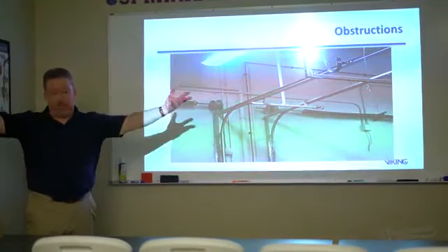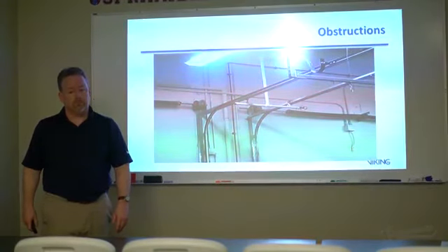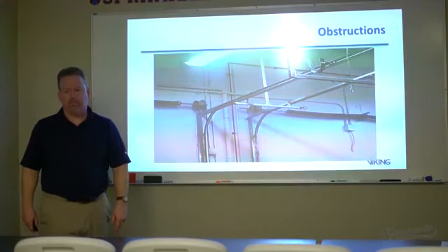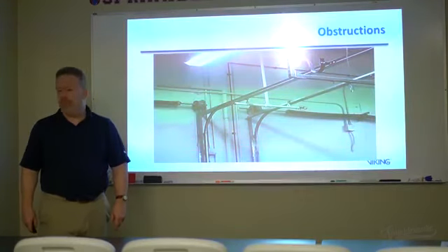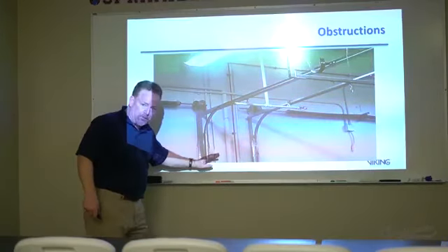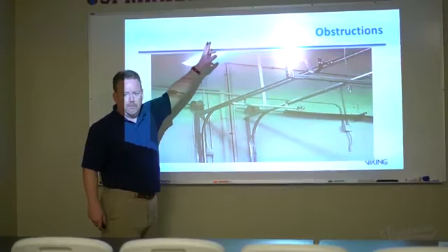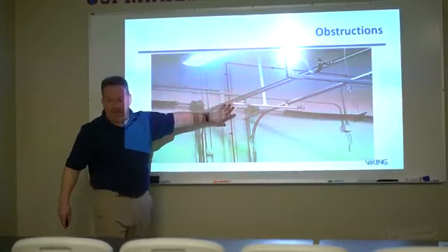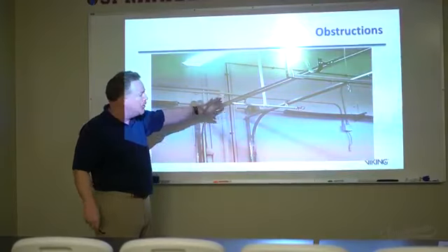Because most doors are 8 to 10 foot wide. The question is that the branch line is you can have it closer. It's going to work when the door is open, below. But I'm saying your distance doesn't matter. No, because if these are closed, what sprinklers are going to provide the protection? The ceiling sprinklers will, and we're not even going to rely on these to do it. It doesn't matter if these get wet from the other sprinklers because we're not relying on these to operate in that case. Okay, only when the doors are open.